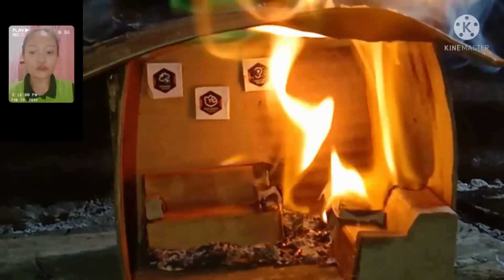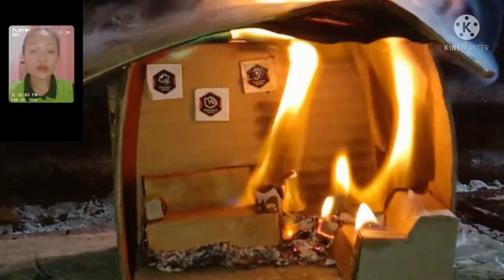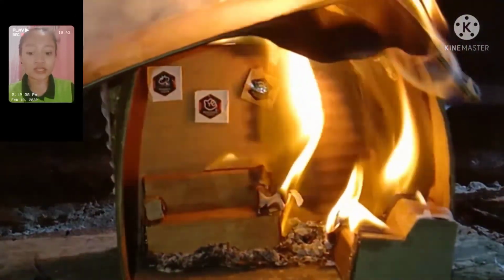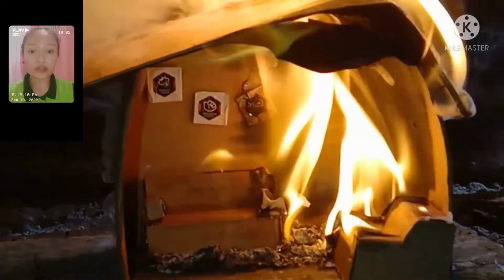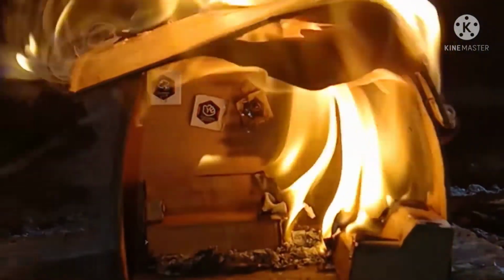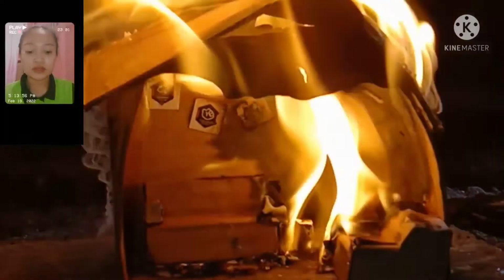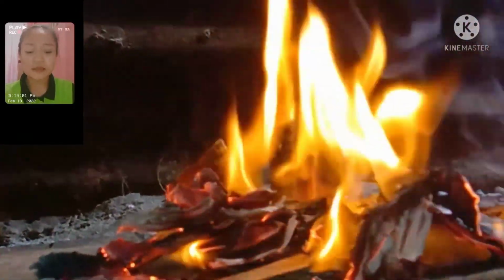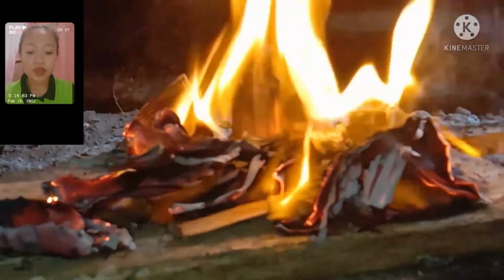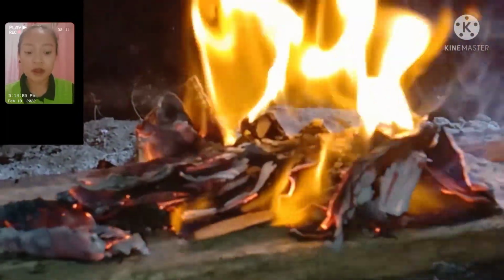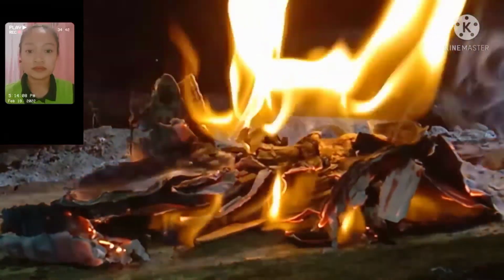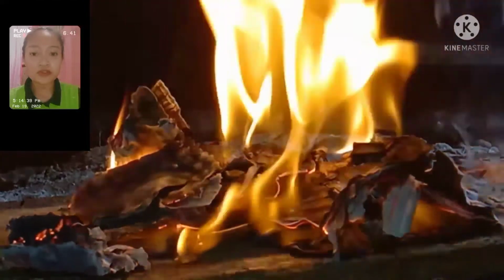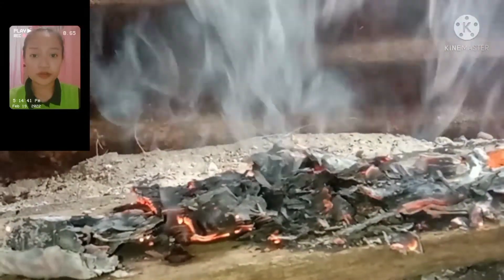The temperature of the room starts to increase. Notice the white vapor coming off. The newspaper pyrolyzes and auto-ignites in a matter of seconds, just due to the radiation from the hot gas layer. This is a precursor to flashover. Notice the turbulent fire conditions until the entire room transitions to flashover.